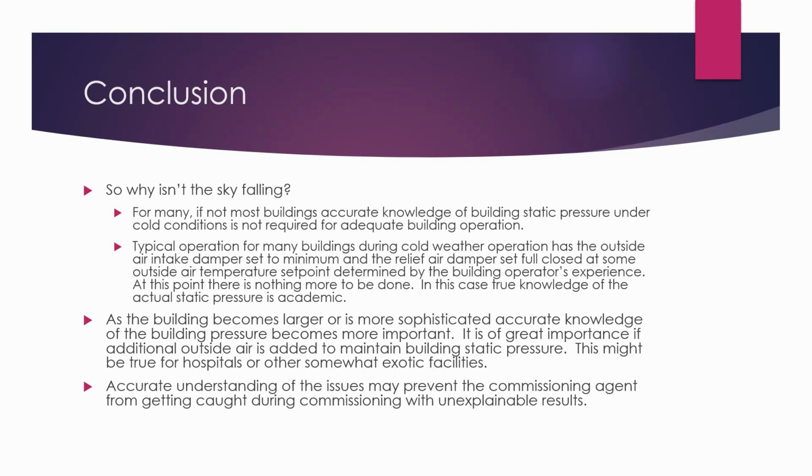So typical operation of many buildings during cold weather has the outside air damper set to minimum and the relief air damper set full closed at some outside air temperature set point determined by the building operator's experience or the sequence of operation possibly. But typically it's something found during cold weather. Once this is done, nothing more can be done. In this case, true knowledge of actual static pressure is academic.